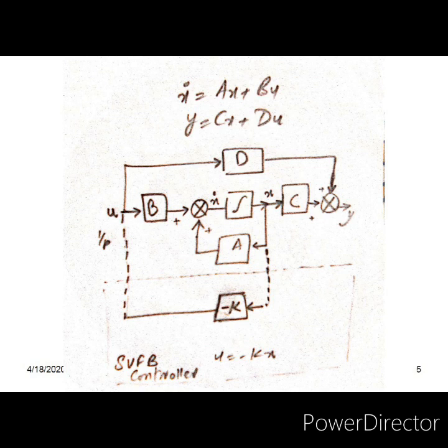The regulator system's purpose is to bring the output to 0, and if you have any kind of problem with that, y equal to 0 means nothing, then my answer is that this 0 actually means the error should become 0. We want to take the error down to 0. That is, the system output does not actually become 0, its error becomes 0. So at the output, that y is error in that sense.